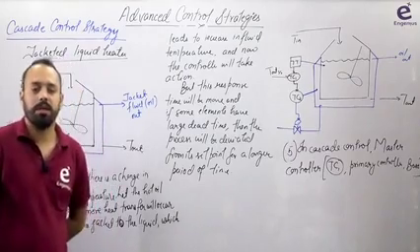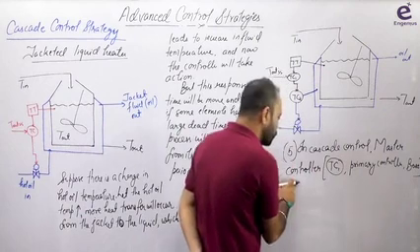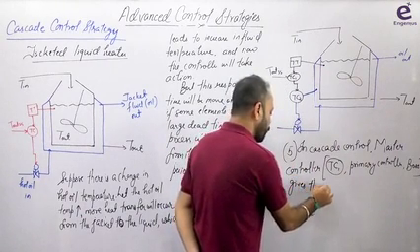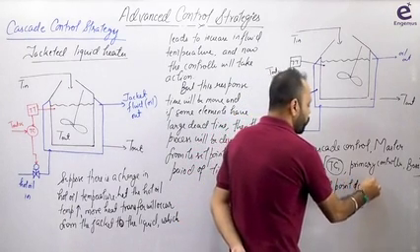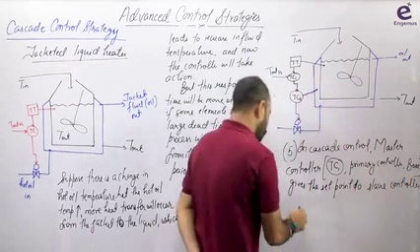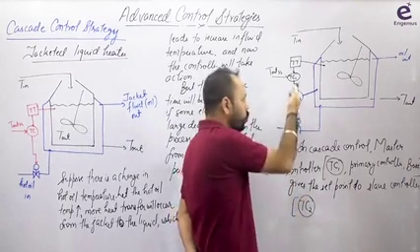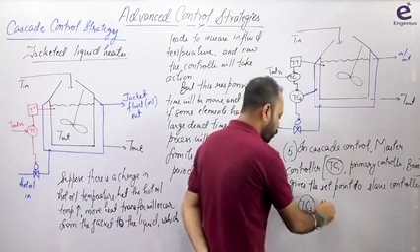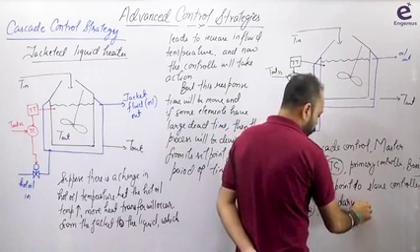You won't say why was this given, whatever he says you have to do. Okay? I'll discuss this again. In cascade control, the master controller gives the set point to the slave controller. And who is the slave controller? What is another name for the slave controller? Either you call it TC2. It's not always TC2, but there are only two controllers here, TC2 and what else? Secondary controller. And you have to understand this as recruit or trainee, secondary controller.